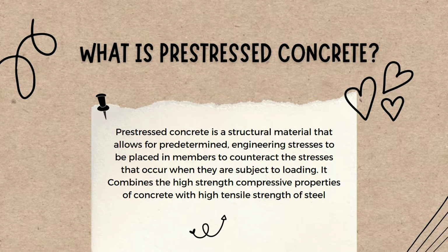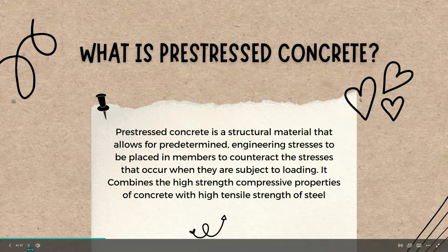What is prestressed concrete? Prestressed concrete is a structural material that allows for predetermined engineering stresses to be placed in members to counteract the stresses that occur when they are subject to loading. It combines the high-strength compressive properties of concrete with the high tensile strength of steel.